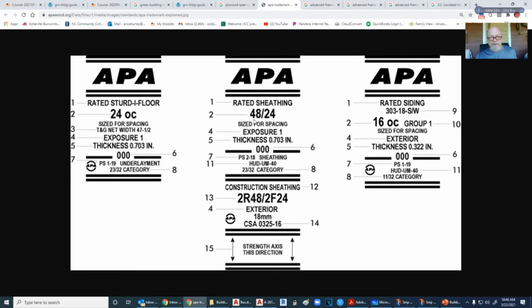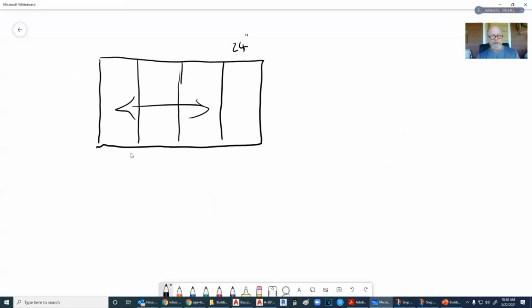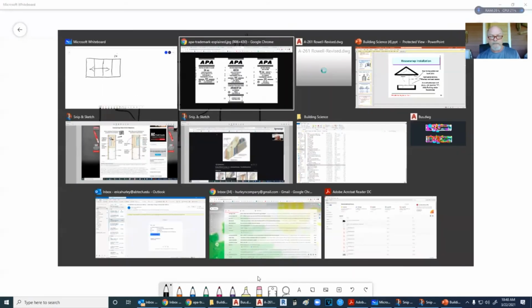All right. So sheathing is a different story. Sheathing goes up and down vertically, so you don't have any weight being pressed down on it. The only thing you have to deal with there is wind loads and so forth. So we still can't do 32 inches on center. You might have to have an inch piece of plywood before you get to 32 inches on center on that.